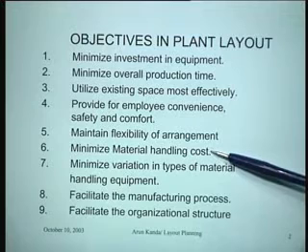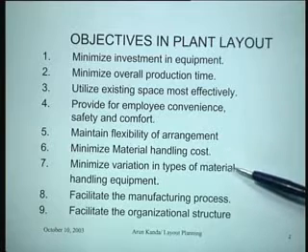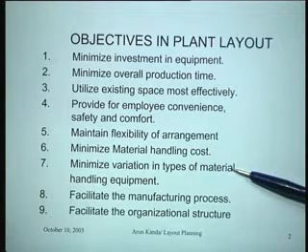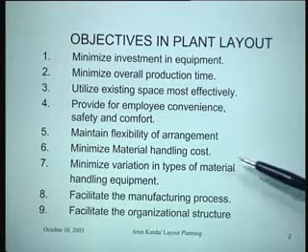A layout generally tries to minimize the material handling cost. It also tries to minimize the variation in types of material handling equipment. For instance, a good layout would try to standardize the kind of material handling equipment that it uses. For instance, you don't expect forklift trolleys of very different sizes to operate in the same shop floor. You would expect standardized equipment.